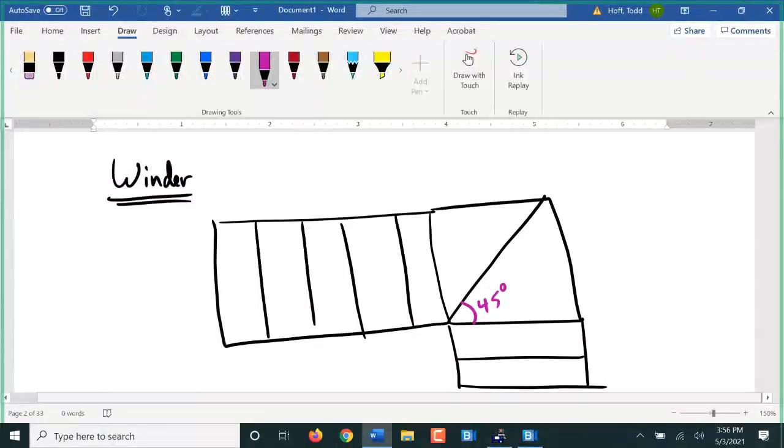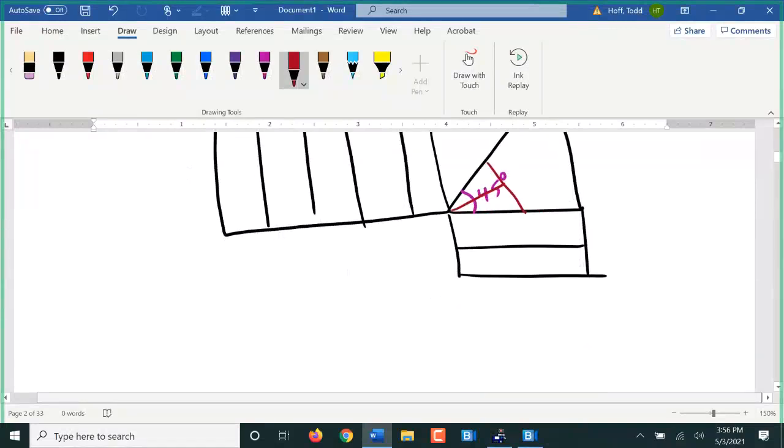So if we only do a 2-step winder on our platform, that would be a 45-degree angle. Well, if we come out 12 inches there, we'll have to have that 7 inches of width. The one we built in the shop was 12. 12 inches out, 7 inches of width. Yep. That's what I thought. So this has to be 3.5. Now there might be some different rules for winders over the spirals, but it used to be the winders covered the same code as the spiral staircase.